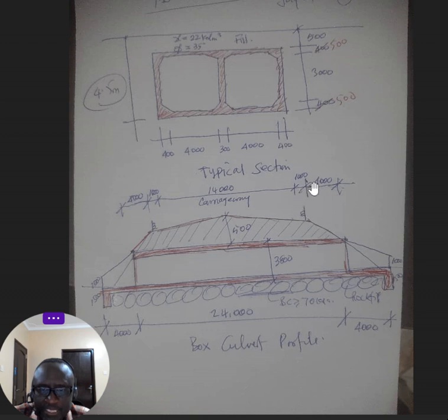Then you have a 1 meter area where you insert the safety guide rails, and then the spread I assume to be 4, but actually you can get the proper value from the actual site condition and the geometry design from the highway engineer. You are able to get exactly what you need to handle. I think this thickness is wrongly put. It is supposed to be 4 because you have 500 and 500. I corrected it up here so that you can see the bearing capacity.